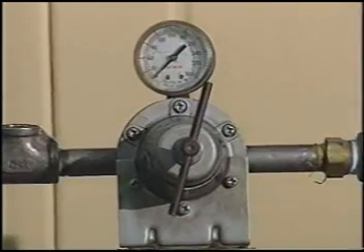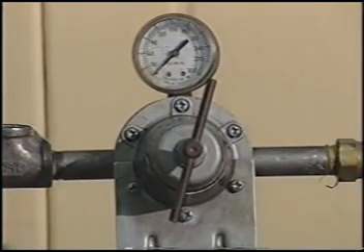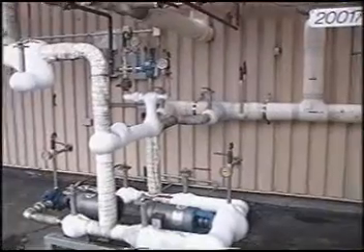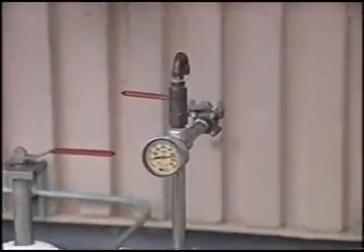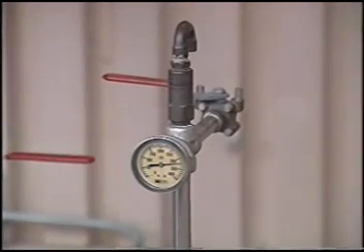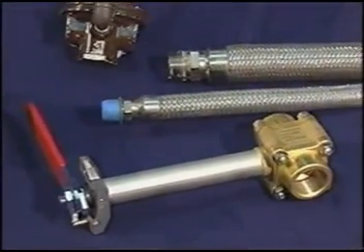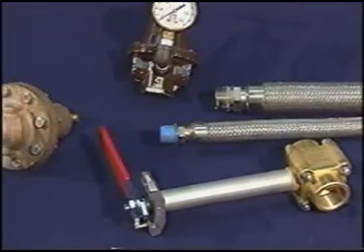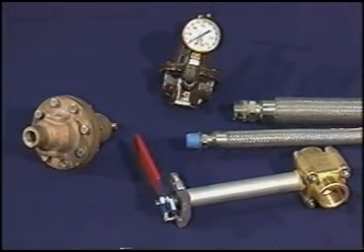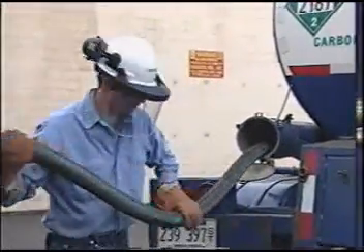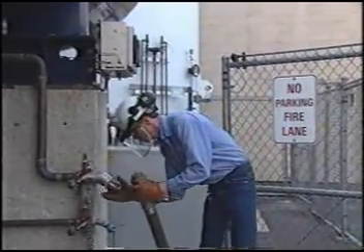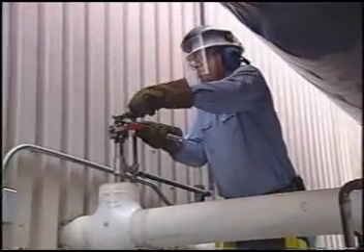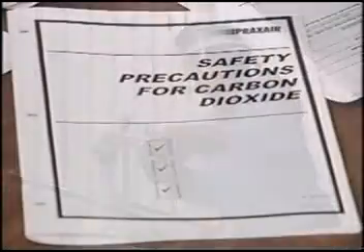To prevent overpressurization, install relief devices in lines where liquid can be trapped. Use pipes and controls that can hold the highest possible pressure with regulators and safety relief valves installed ahead of hoses and low-pressure equipment. Prevent damage to pipelines, valves, hoses, containers, and other system parts by using materials that can handle the extreme temperatures and pressure. Avoid personal contact with carbon dioxide by wearing eye or face protection and insulated gauntlet gloves. And wear long-sleeve shirts and trousers without cuffs.